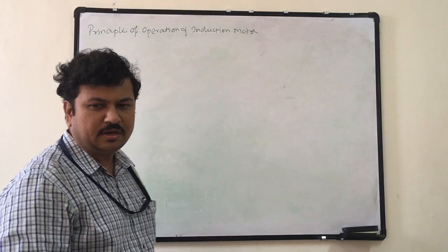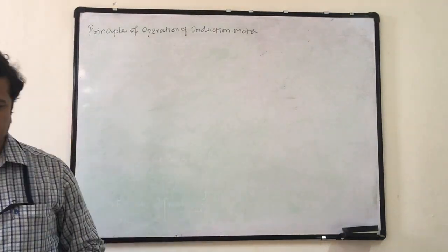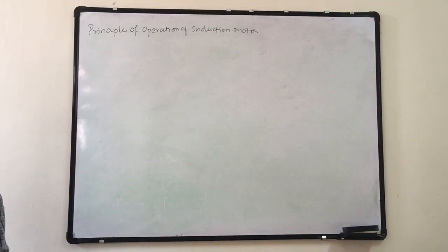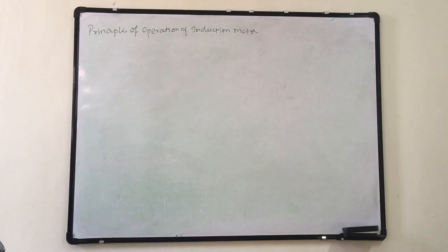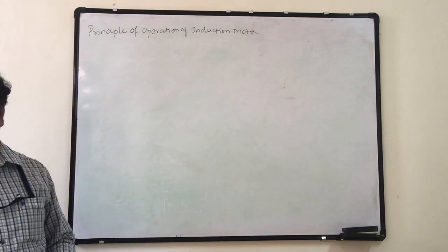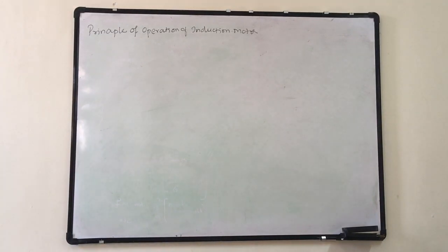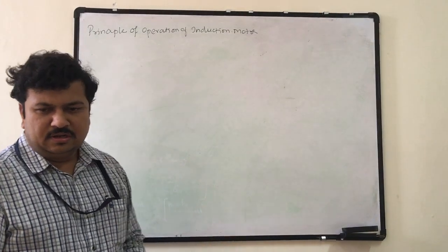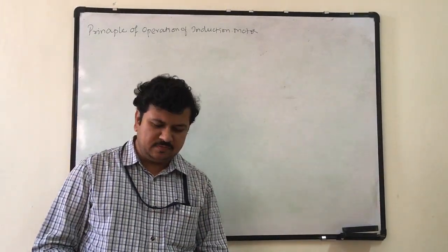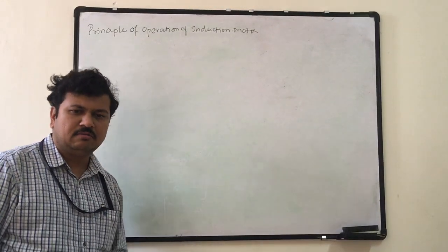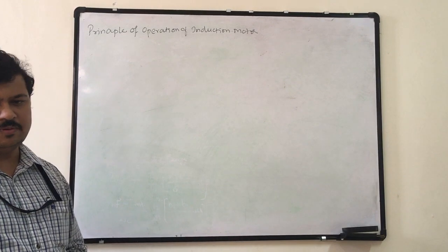The rotating magnetic field in induction motor. Okay, so there we saw how when we apply the three-phase supply to the stator, and when three-phase currents are drawn by the stator winding, we get a three-phase flux operating in the same space, that is in the same air gap, and when those three fluxes interact with each other, we get a rotating magnetic field with respect to the change in the omega t value of the supply voltage.